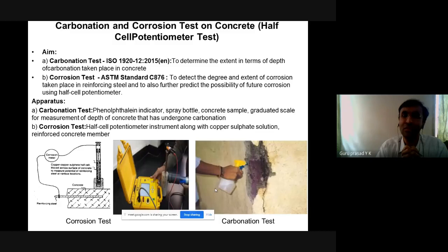Reinforcing steel, copper, as well as gold and silver are ductile materials. Concrete is, I would use the word, quasi-brittle. It's not exactly brittle, because you have a post-peak part in concrete. Post-peak softening takes place in concrete when you subject it to compression, meaning concrete will just not crush like glass or cast iron.